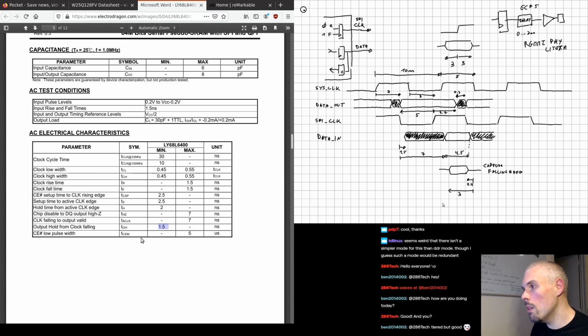If you miss timing by 100 picoseconds, don't worry about it because these are just typical numbers and average. So in this particular example, it turns out that sampling on the falling edge probably will work and probably will work reliably. Because some of them are worst case, like the data from the flash, they're worst case, right? So it's going to be slightly larger than that. So I have full confidence that for the flash running at 100 megahertz, using those timings, it's going to work, right?